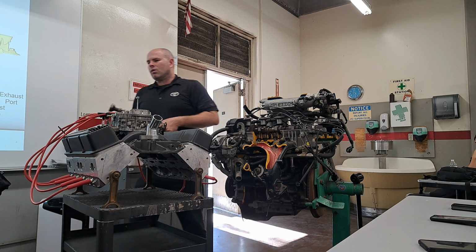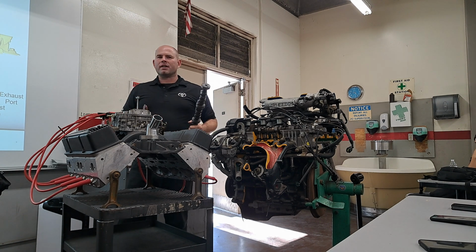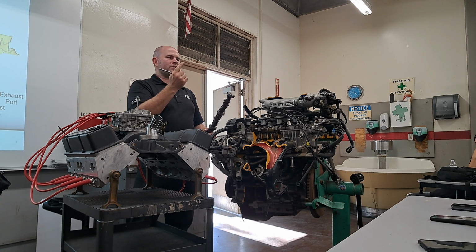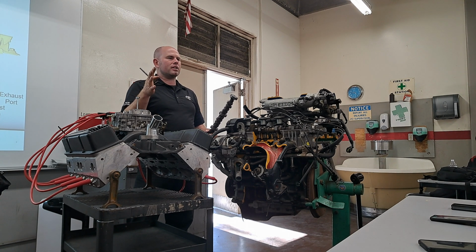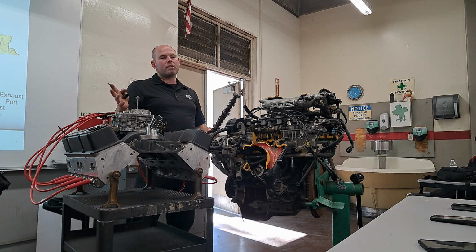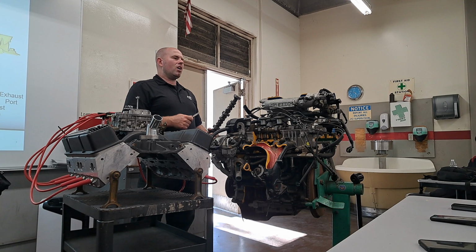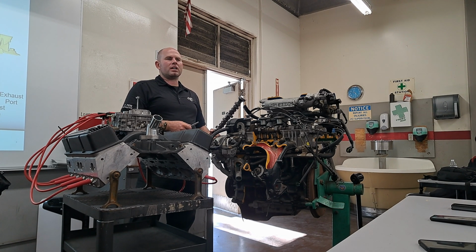I don't like the bikes, but Ducati, for example, actually has a cam to push the valve open and a cam to push the valve closed. There is no valve float. There's no spring. Doesn't need a spring. I don't know about all of them, but I know in at least one of them. So the logic behind that was, you want to do 16,000 RPMs for the whole race? No problem. You're not going to have valve float.